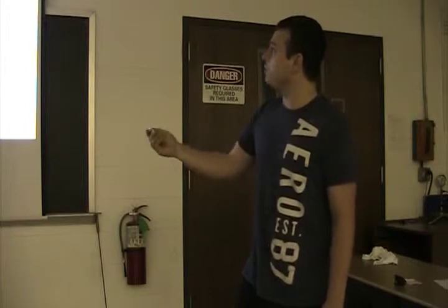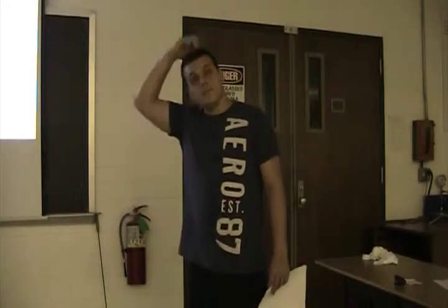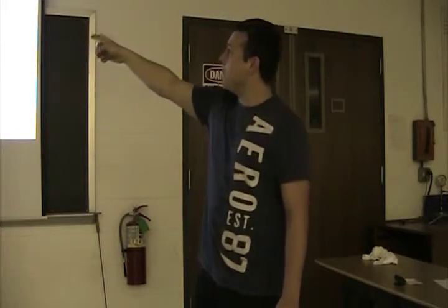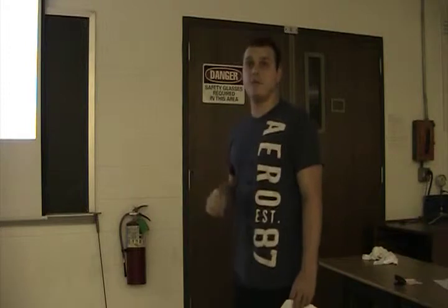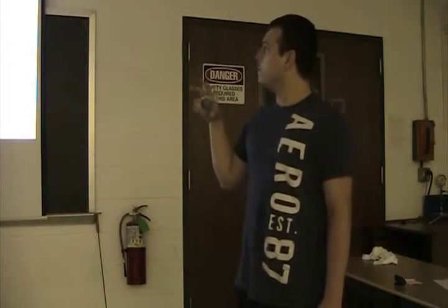All right. Then you have a supersonic ejector. With the supersonic ejector, you have your steam coming in, your working fluid, which is accelerated to a speed of Mach 1 in the throat, and then it comes out of the diffuser, continues to accelerate, and is expelled into a suction tank.